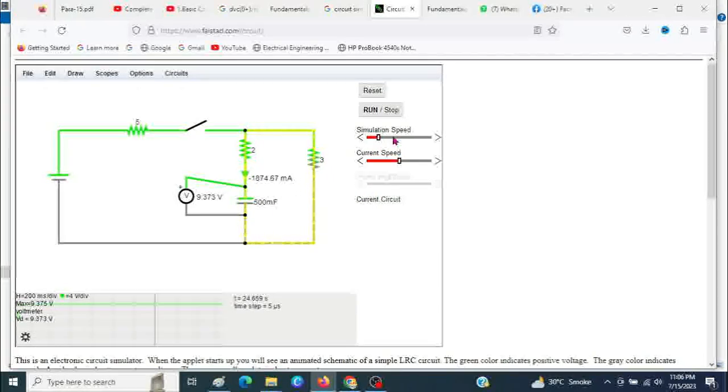Now this we are clear. So now let me go faster. Increase the speed, and you can see now it is discharging, it is going down. This is the discharge path. One of the questions was what will be V infinity. V infinity means for a very long time when the switch is open, when the capacitor has fully discharged through this. So logically it should discharge to 0, and we'll see that.